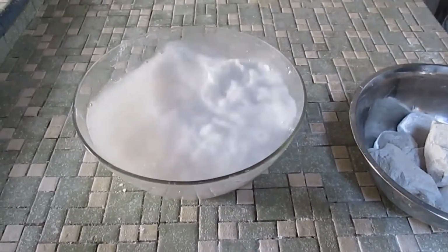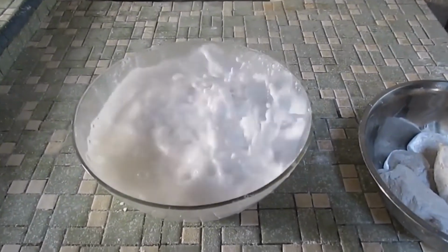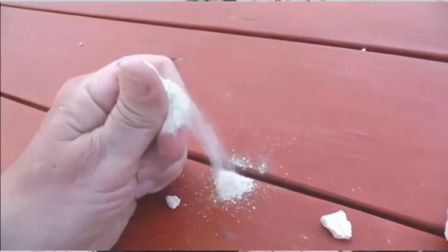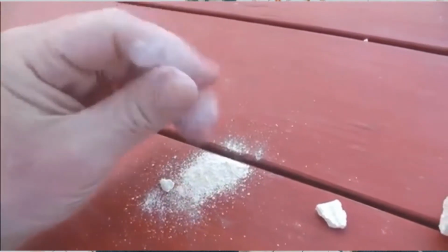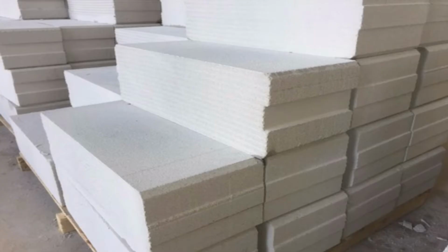The first one is wet slaking, which will produce lime hydrate slurry. The second one is dry slaking, which will produce calcium hydroxide in the form of dry powder. And the third one is lime hydrate from calcium carbide, which will produce calcium hydroxide as a byproduct. Steam-hardened construction materials involve large quantities of quicklime that are used in the manufacture of sand lime bricks and aerated concrete blocks.